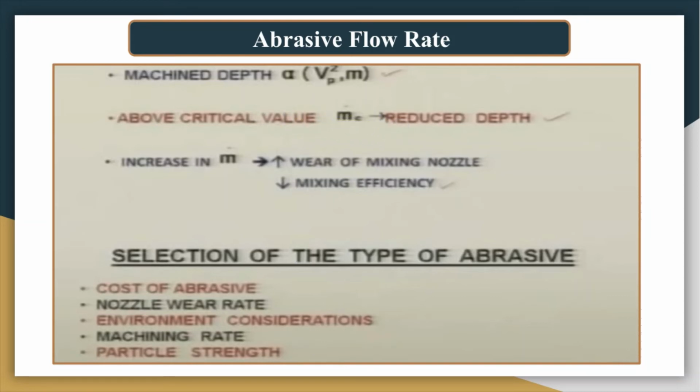Increasing mass flow rate leads to wear of the mixing nozzle, and higher wear of the mixing nozzle leads to reduced mixing efficiency, and that is why there is always an appropriate or critical value of the mass flow rate of the abrasive particles.